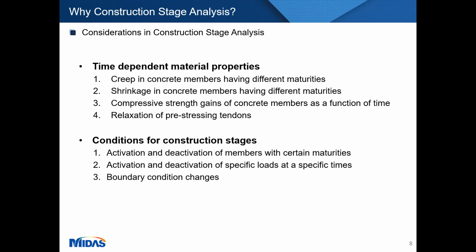Similarly for boundary conditions as well. Suppose during construction the boundary condition is changing. For example, we are doing a full cast in situ construction. In that case, the deck will be completely supported till 28 days, and after that the false work will be removed. So these types of boundary conditions will change during construction, and that needs to be taken into account.